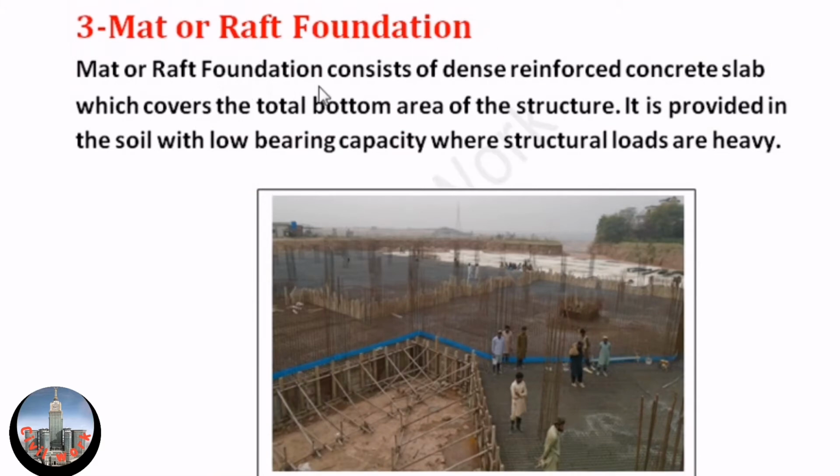Number 3. Mat or raft foundation. Mat or raft foundation consists of a dense reinforced concrete slab which covers the total bottom area of the structure. It is provided in soil with low bearing capacity where structural loads are heavy.